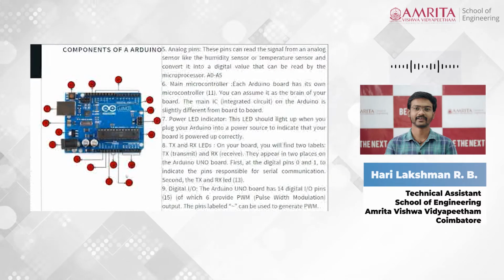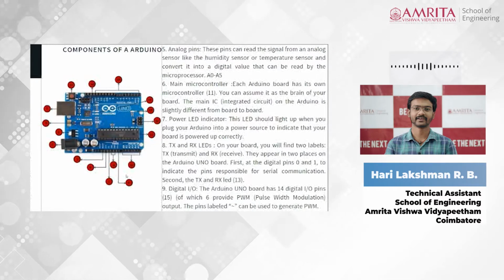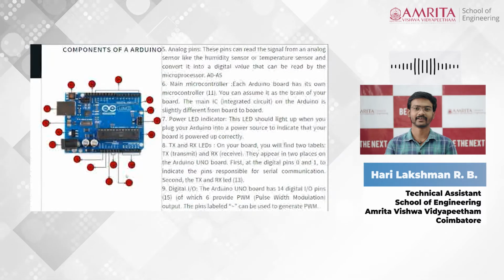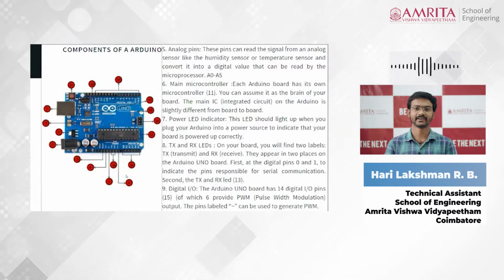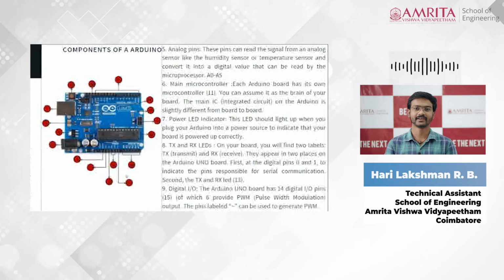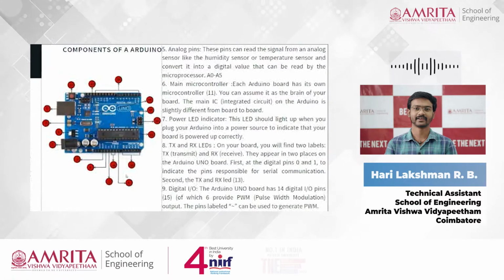Next, the power LED. This LED should light up when you plug your Arduino into a power source, to indicate that your board is powered up correctly. If this light does not turn on, there is something wrong with your connection. You need to check it using the feedback from the LED.